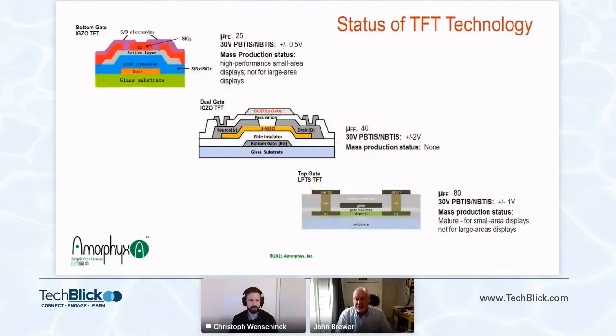While amorphous silicon supported TFT performance sufficient for the early days of LCDs and continues to be sufficient for commodity-grade image quality and power consumption, silicon is far from capable of meeting the requirements of high-performance, small area and large area OLED and micro LED displays. Speed, output current, physical size, stability, power consumption, and manufacturability are uncomplementary TFT parameters. To improve one, the others are compromised.